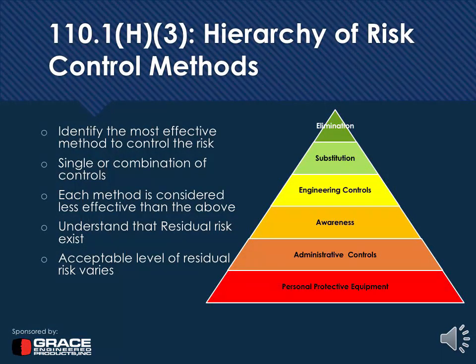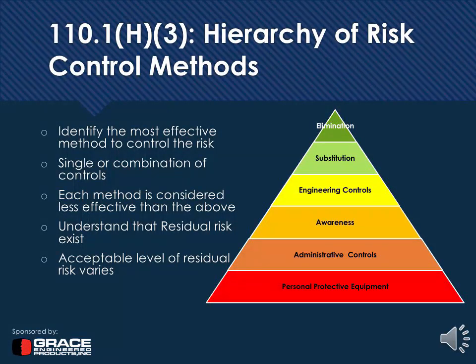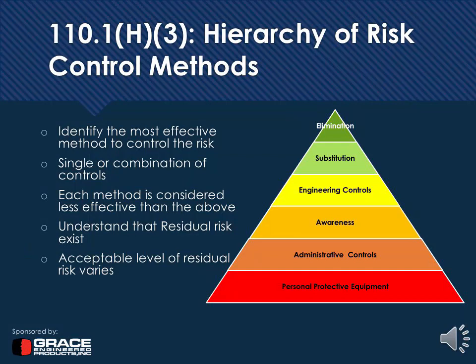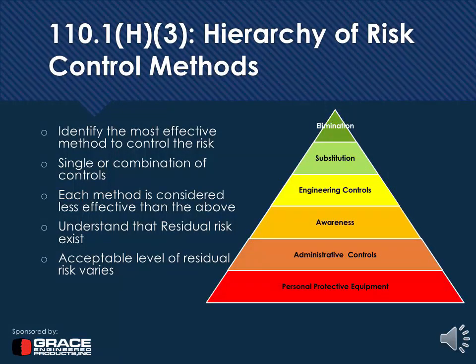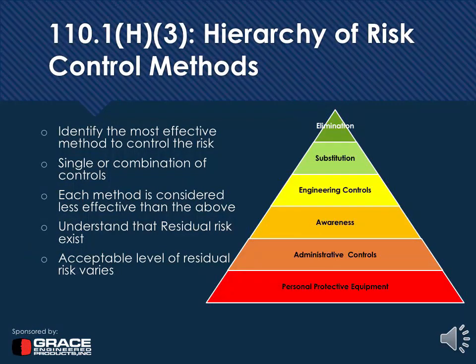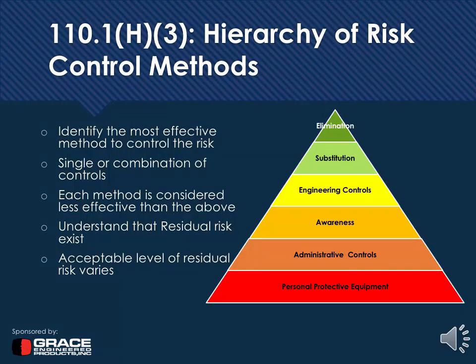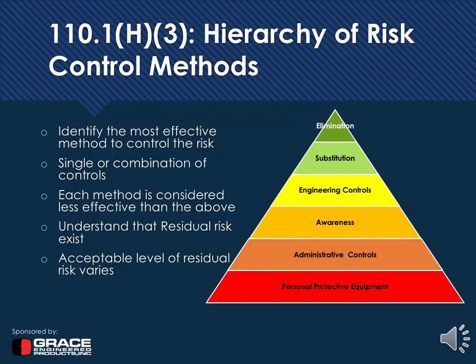Some of the engineering controls are remote racking, interlocks, both mechanical and electrical, or any kind of door-mounted devices for measuring or performing the absence of voltage testing. How do you minimize through design itself, right? So those are the engineering controls. And the awareness, any kinds of signs, labels, warnings, and alarms, those things that will be given. But understand that awareness is going to be impacted by human error coming into play. So basically how an operator or a maintenance person is going to interpret that awareness, and the environmental conditions, is going to play a significant role in it.